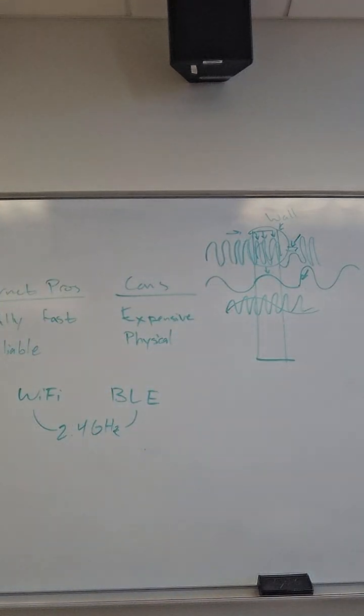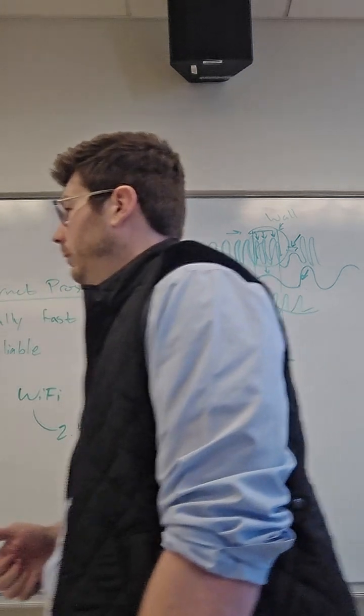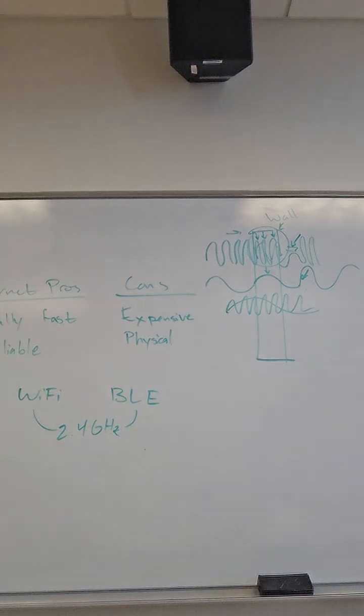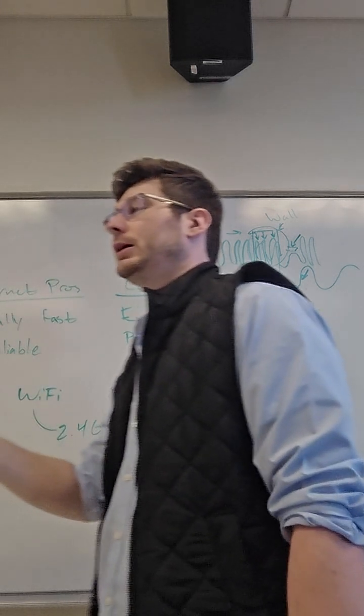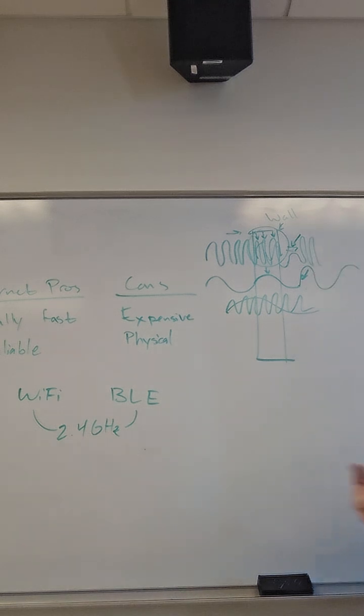But if you have some gateways scattered around that are in sight of one or more of those sensors, you can use that gateway to jump that information up instead, where that gateway would have both either Wi-Fi or Ethernet and a BLE sensor in there as well, so it would turn BLE communication into LAN communication that goes up to the cloud. Okay.